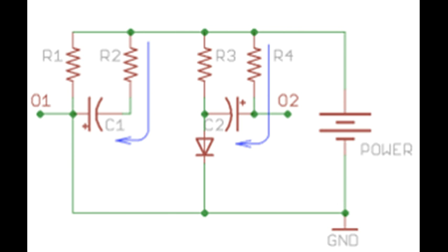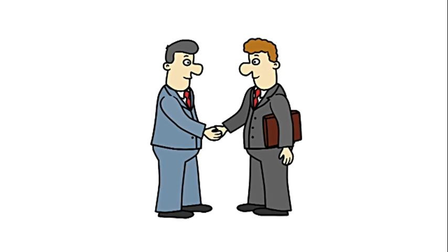As C1 continues to charge, the next critical moment happens when C1's right lead rises. At that point, T2 will conduct again while T1 shuts off. The same cycle will repeat. So by now, Harsh, you must have understood the basic working of the oscillator and also the basic working of the inverter.